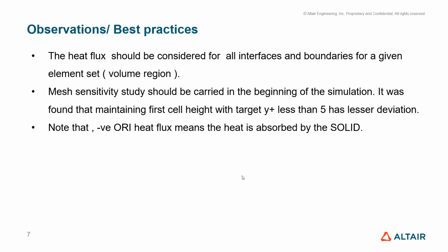And also a mesh sensitivity study should be conducted at the beginning of the solution. And in the past, targeting a y plus of less than 5 gives a lesser energy deviation, lesser energy imbalance. And also negative heat flux for radiation means it is absorbed by the solid.